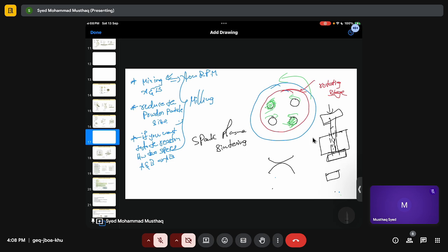In this pellet, the powder particles are touching each other, which is obvious, and then you apply current. Whenever the current flows inside the powder particle, it is okay, but when it is crossing the path between particles, you have a resistance, which you can call contact resistance. And whenever you have a resistance, I hope everyone remembers, Joule's heating. Whenever you have resistance, you have heat, right? And also we are supplying very large amounts of current in spark plasma sintering, right? So that's how you have a localized melting spot.